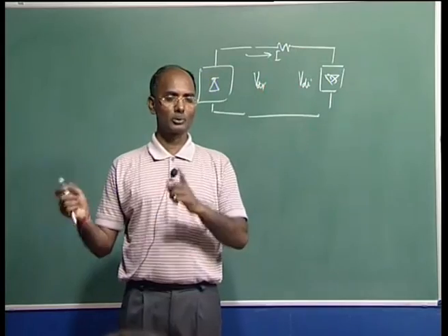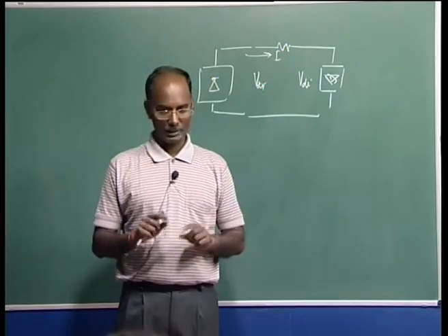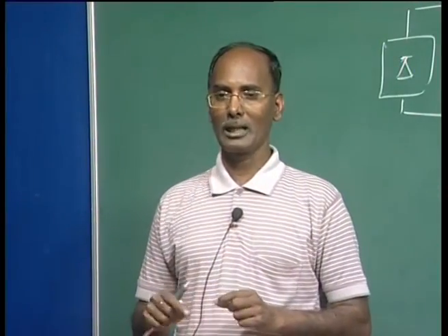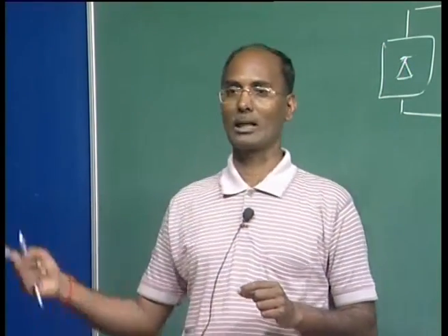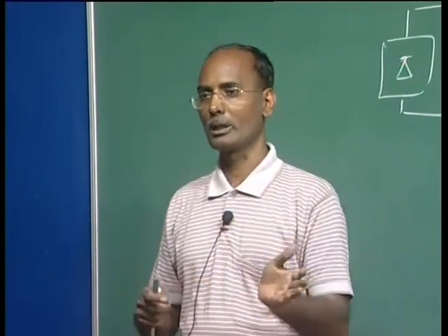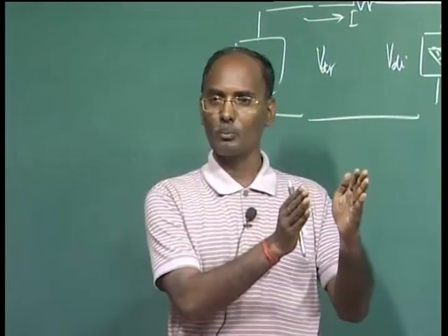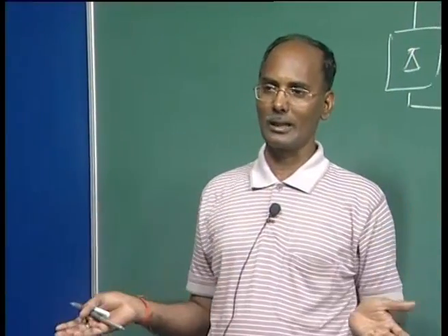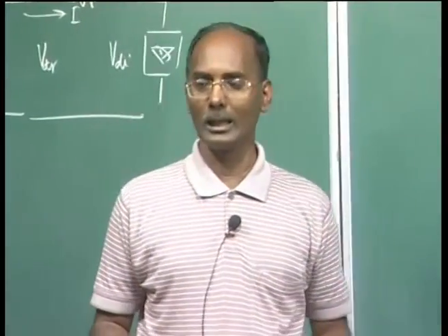Next the turn will come to 6, and we will find that 6 will conduct, because the 1 and 4 commutation will be successful. Then the 6 and 1 pattern is coming, and after that 1 comes, which is already conducting, so there is no problem. So 6 and 1 will continue, then 2 will come, and then 1 and 2 will be there. So in the whole cycle we now get our 1 2 pattern, and finally we are also getting 1 2 and so on. So it is automatic clearing. The commutation failure is a self-clearing phenomenon in a single cycle if it is a single one.